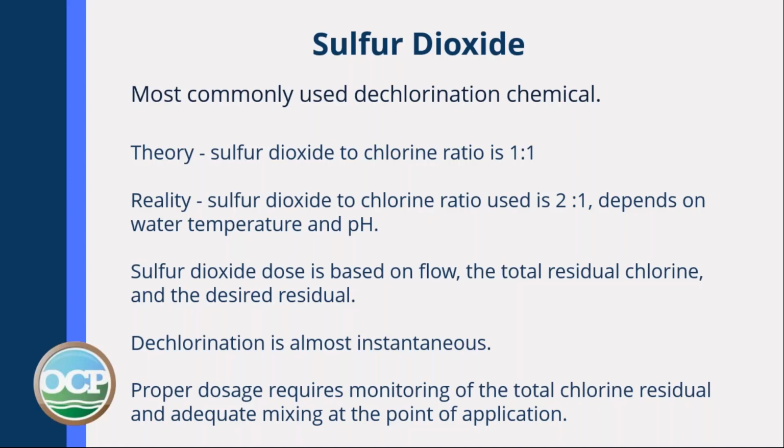Sulfur dioxide dose is based on the flow and the total residual chlorine and what kind of residual you're shooting for, which for most wastewater guys is 0. Dechlorination is almost instantaneous. Proper dosage requires monitoring of the total chlorine residual and adequate mixing at the point of application.